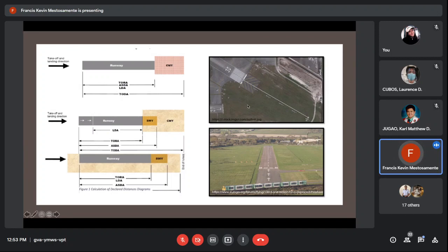This is a grass area. This part is the boundary of the airport, and I think you have a road here in this example. As you could see, there is no obstacle here. It is an obstacle-free zone since it's part of the clearway that will be part of the initial climb of the aircraft. On the lower right-hand side of the slide, you could see an example of a displaced threshold. You could see the arrows provided. We probably have an obstacle around this area ahead of the landing part, which is why the threshold was displaced. And you could see here a landing perspective of the crew, and I think it's on the glide path as I could see.